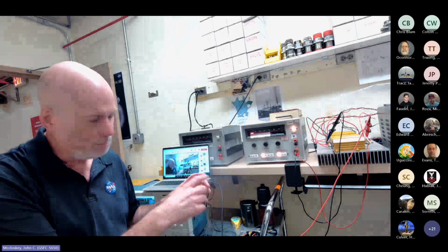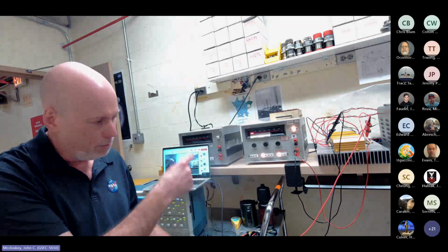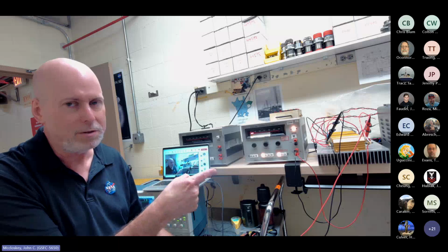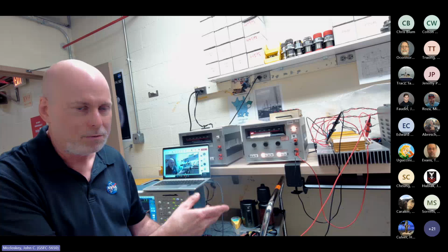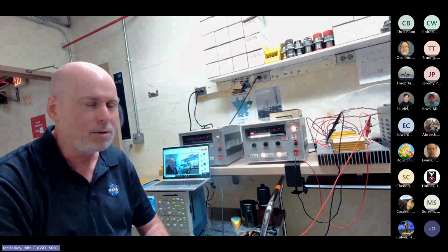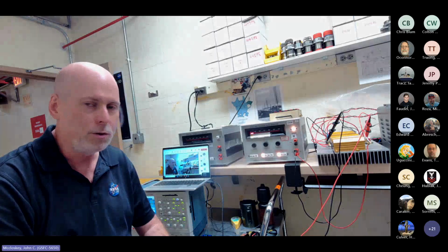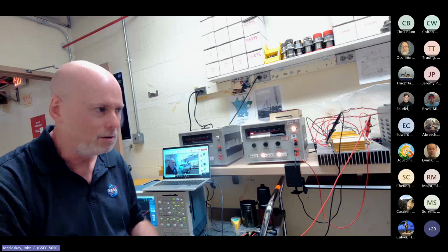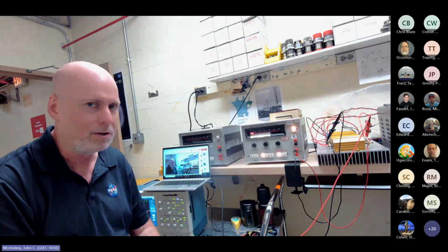It drew over 30 amps for about 25 milliseconds, and it pulled the bus voltage down by all of about half a volt for those 25 milliseconds. So had I known that before we were putting all the individual boxes through their test campaigns, I would not have bothered applying CS06. It was not really a worthwhile test for a power system that could absorb those kinds of transients in a pretty benign manner.